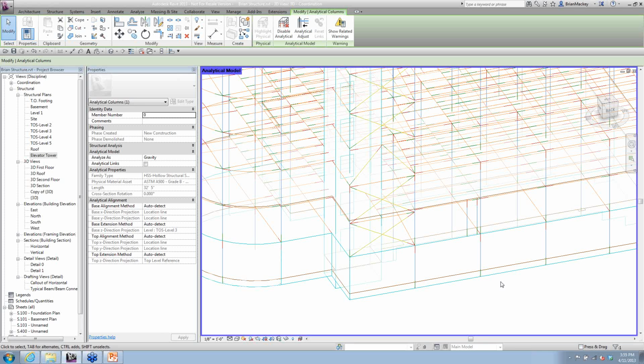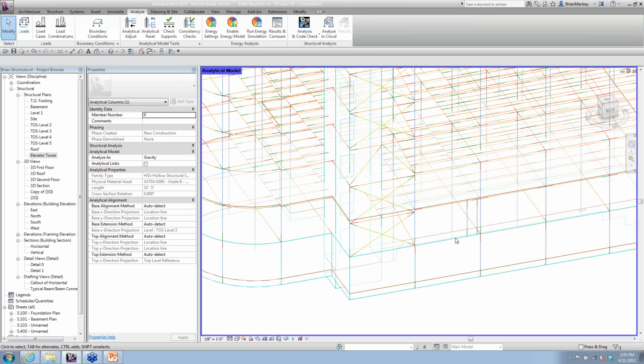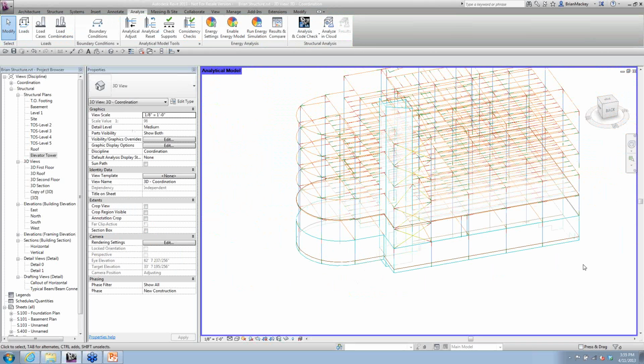So she's not an expert in all of the analytical programs, but it's definitely one of those things that she goes through and did. And it's something that one of the architects online said it's something even an architect could understand. So it kind of lets you know how you need to get this stuff set up. But the key thing is, don't yell that Revit doesn't export, it just doesn't understand it. Come back through and check the analytical things. Make sure it's going to be there, and try some small exports out to your analytical program.